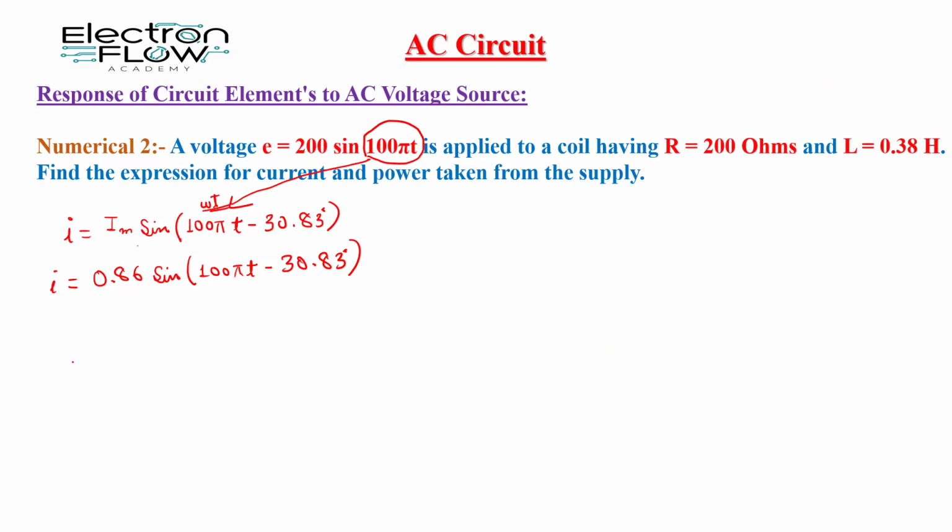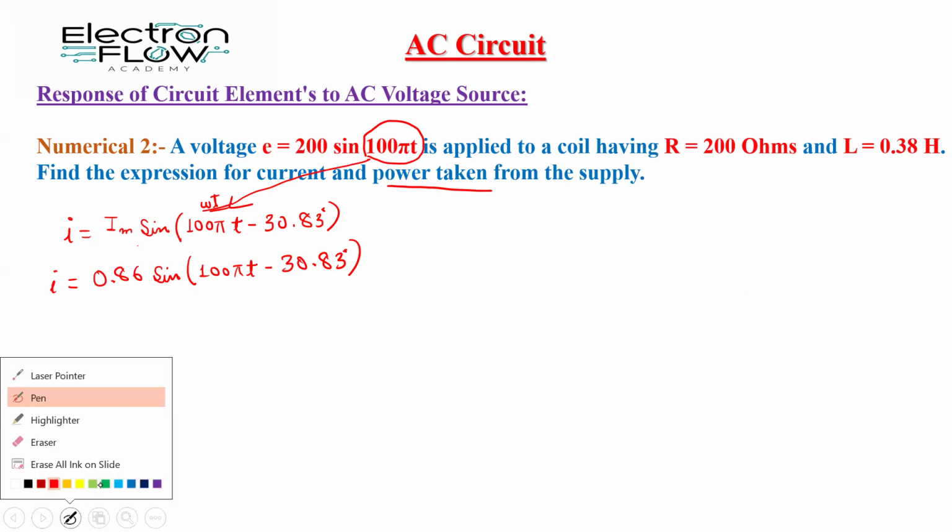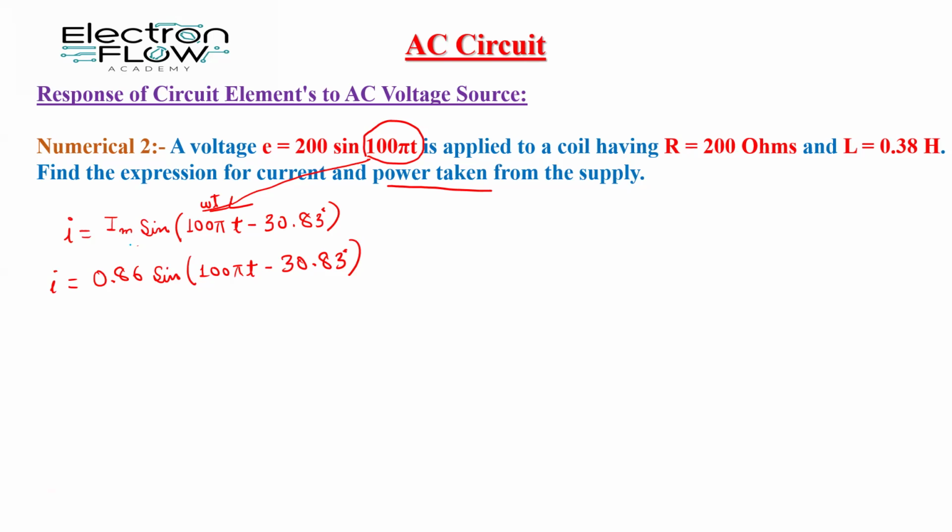Now another thing asked in the question is the power taken from the supply. Next we need to calculate the power factor. The power factor is nothing but cos phi, where phi is the phase angle difference between the voltage and the current.